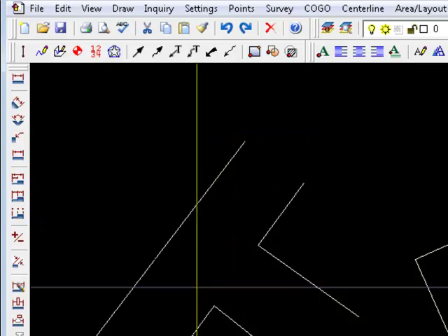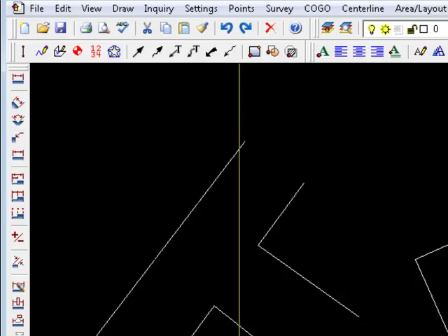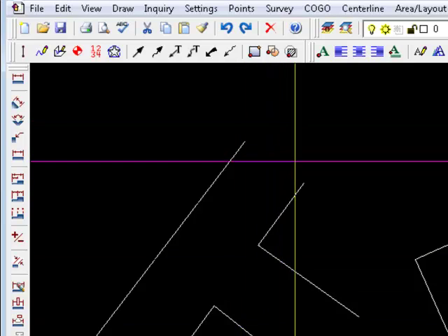And at some point you may see on the command line it says undo end, meaning it has undone everything you've worked on to a point where it now needs to go to a database that it has created to allow you to go further back. Hopefully you won't see that too often, but it will let you continue to go back and back and back. It can be a lifesaver. So undo, another very important feature.